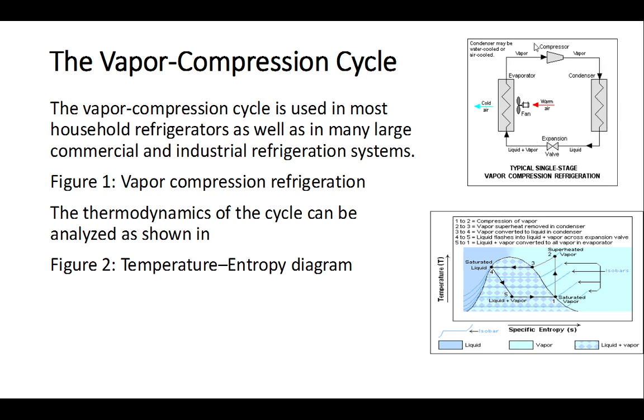So we've got this circle, where it goes from vapor through the condenser to liquid, then the low pressure area on the other side, and then we've got liquid vapor, and it goes through the evaporator, and energy needs to be put in there to turn it into vapor. So this energy is taken from the environment, and we get cold air coming out of it.